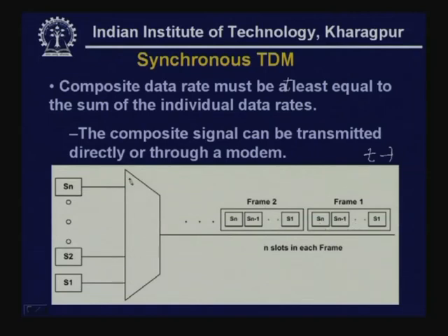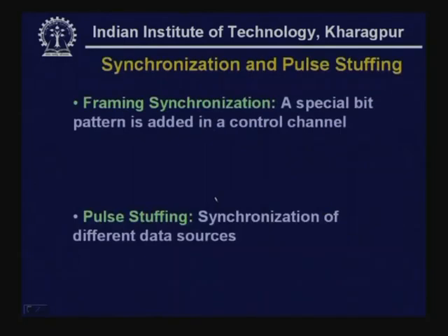So, these are scanned one after the other, then a frame is sent, then comes the next frame, again taken from another source, 1 bit or more bits, then from channel 2, source 2, 1 bit or more bits, in this way it goes up to channel n, and again it is repeated. This is how the scanning is done.